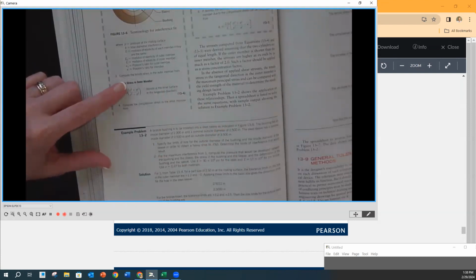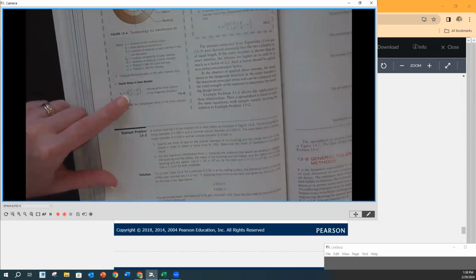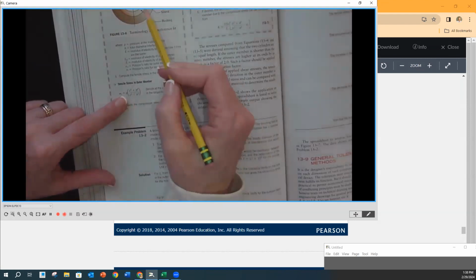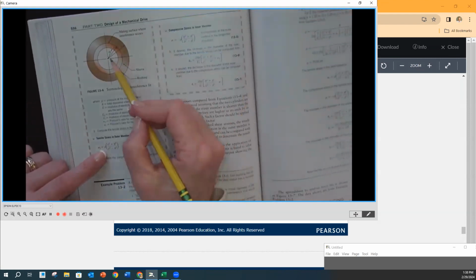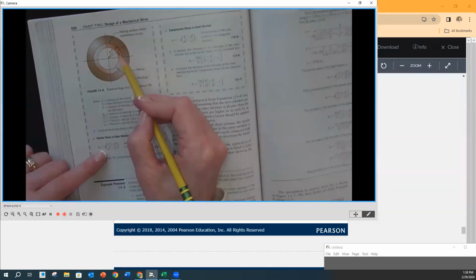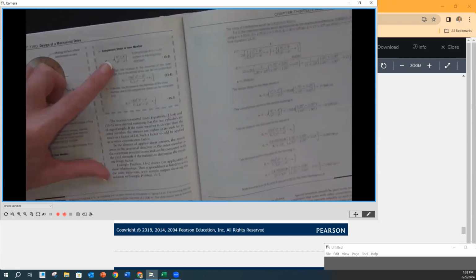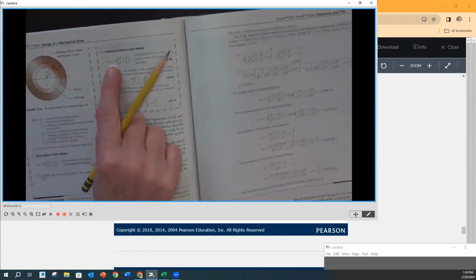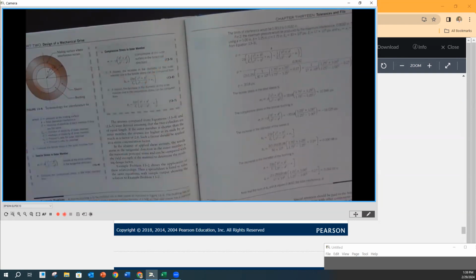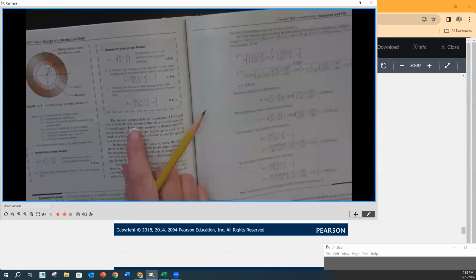Now, to get the tensile stress, we're going to use that pressure, okay? And on the outer member, we're going to use the C and the B dimensions. So you're going to notice here there's C to the outside, the radius, and then B to kind of like the surface of interest where the interference is occurring. And then for the compressive stress on the inner member, we're going to use that very same pressure, but negative this time. Compression is gonna be in the opposite direction, so tension is always gonna be a positive stress. Compression is gonna be a negative. You would have, again, seen that in strength of materials. And that's that same thing here as we see it.